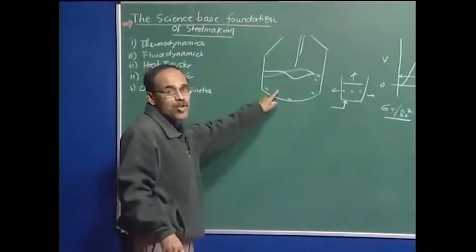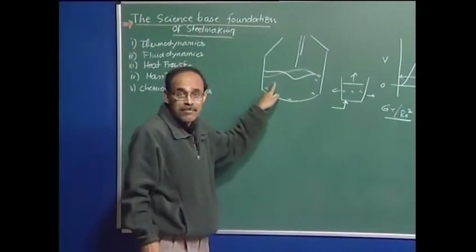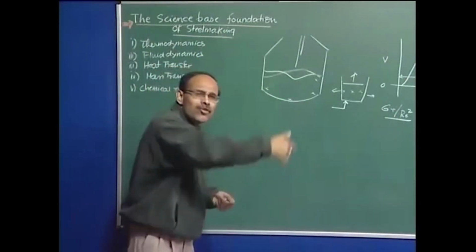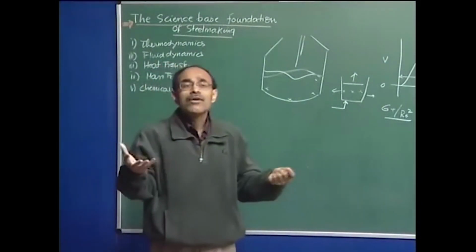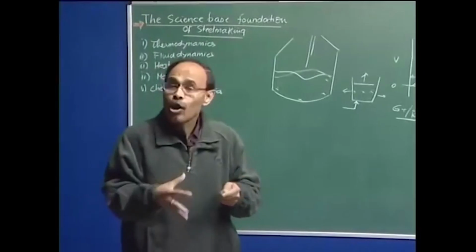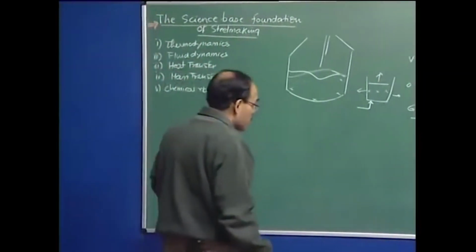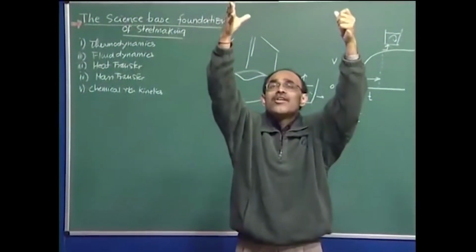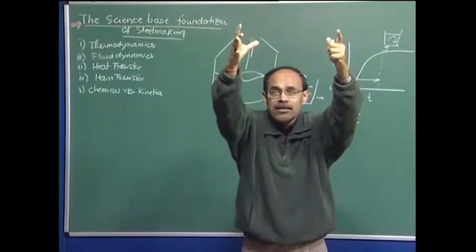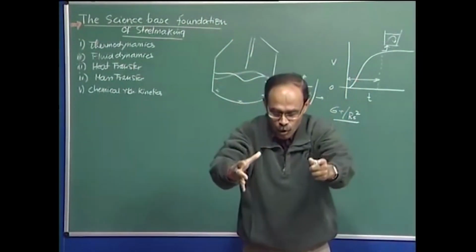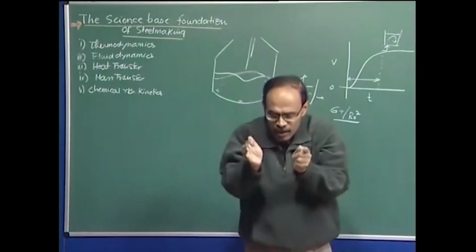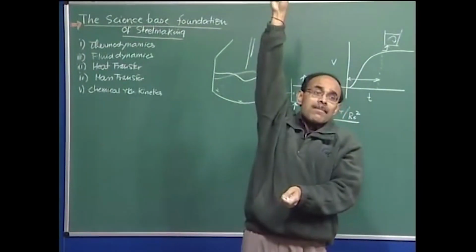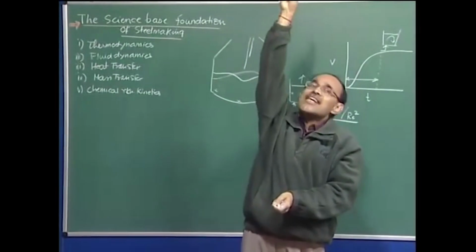So in steel making systems where we have concentration gradients and temperature gradients, we will see that the fluid flow or melt flow could be a result of the combined effect of thermosolutal convection in addition to forced convection. For example, in continuous casting, suppose you are considering a bloom casting and you know that there is a metallurgical length, and towards the lower part of the metallurgical length we have a little bit of liquid core and everything else is solidified, and there you virtually do not see the impact of the SEN, because the SEN is located much higher.